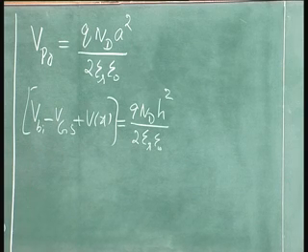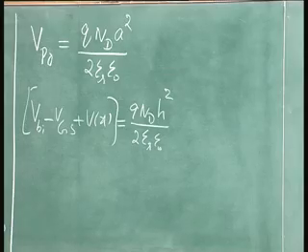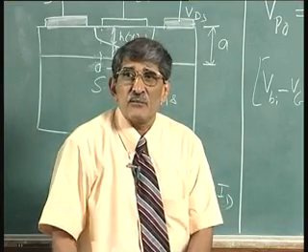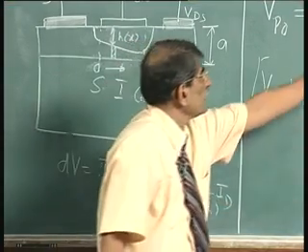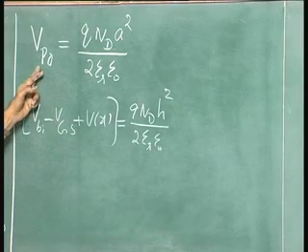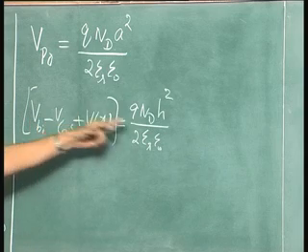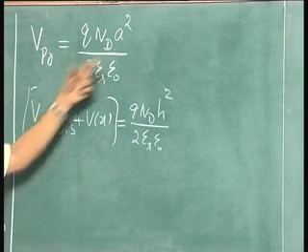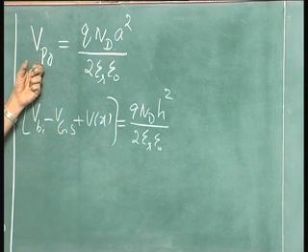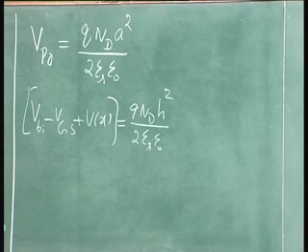Notice now, hereafter we do not have to rewrite this. The depletion layer widths are proportional to square root of the voltage across that. A is proportional to square root of V p 0. H is proportional to the square root of that voltage there. Divide H by A, you get square root of this divided by square root of that. So, that is what we have done.